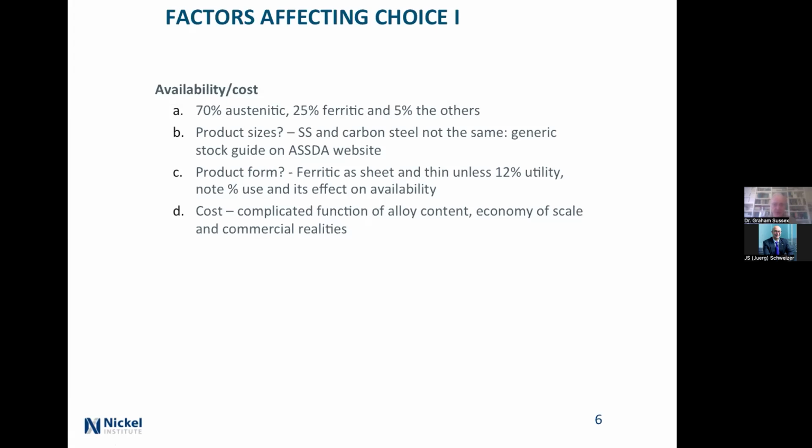As for product form, ferritics will only come in sheet, and they're going to be no more than 4, 5, perhaps 6 millimeters thick, unless you're talking about the utility ones, which are easily weldable and formable and so on, but they only have about 12% chromium in them. So they're not a high level of corrosion resistance.